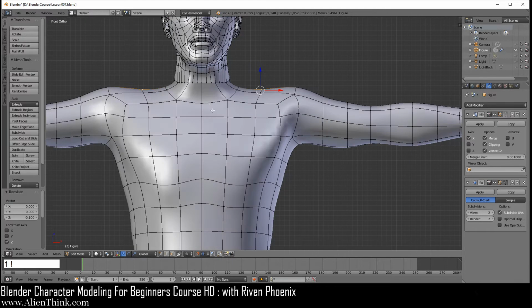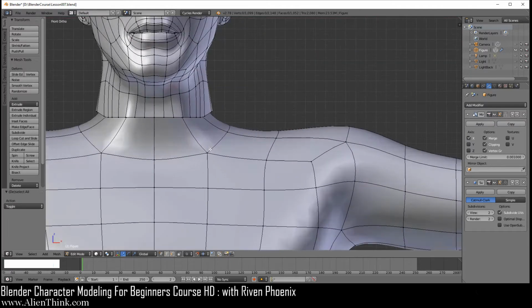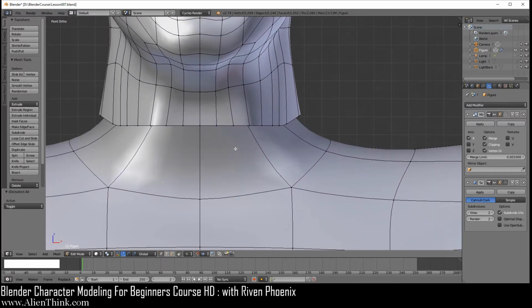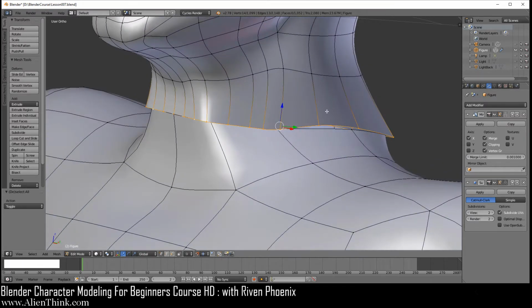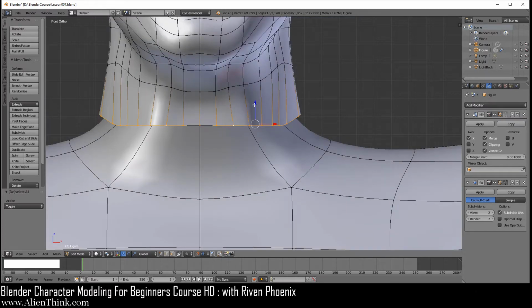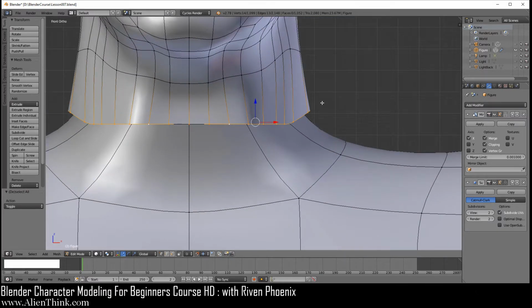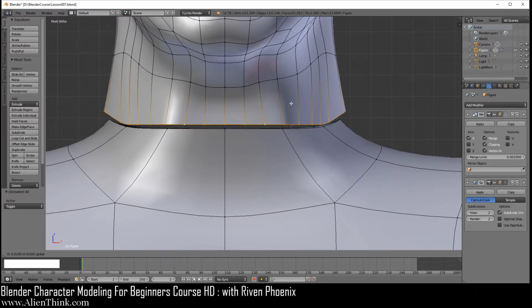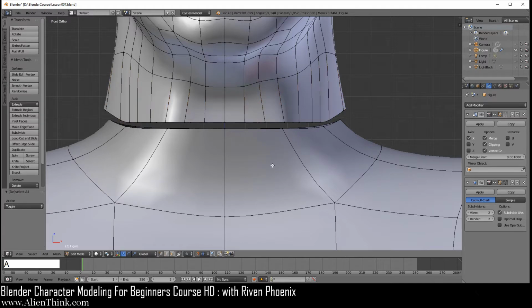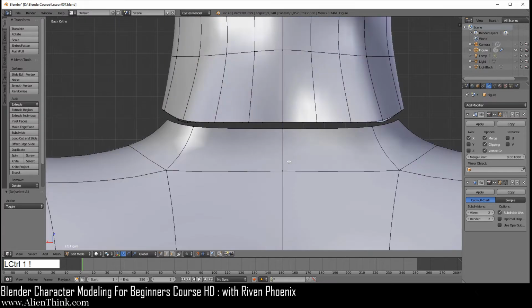So here I'm just going to show you, there's several ways of doing this, but we're going to do this the easiest way, which is right click this. Oh, I'm sorry, you do Alt and right click. You do deselect Alt and right click this. So it simply selects this top area here for the head and stay in your front view. And you're going to zoom in so you get the smaller grids here. And you're just going to pull it up 1, 2, 3. You can do 4 over here, okay? And then A to deselect. And then do Control 1 to go into your back view.